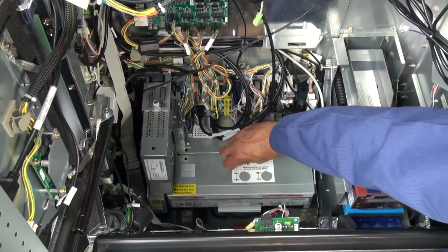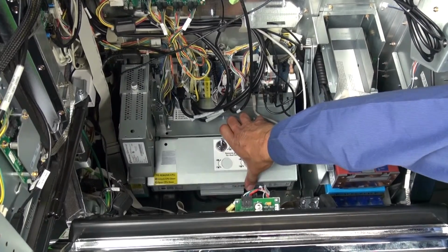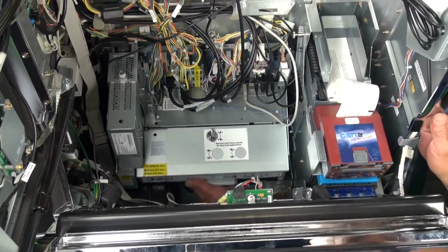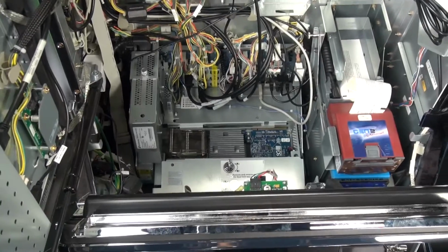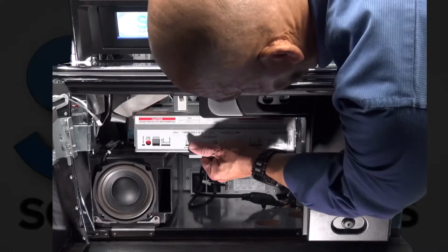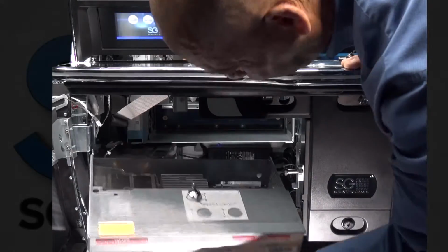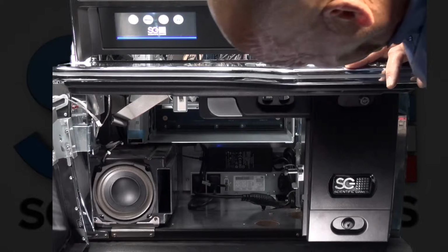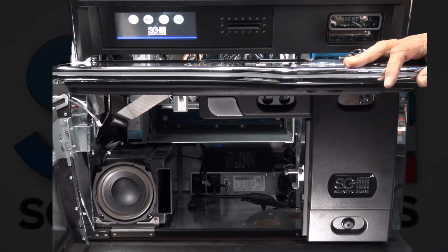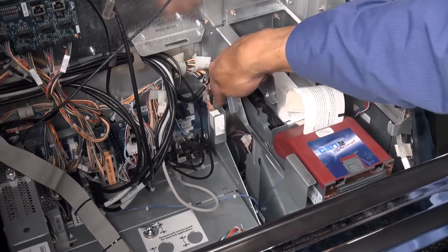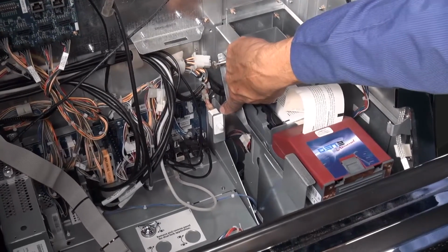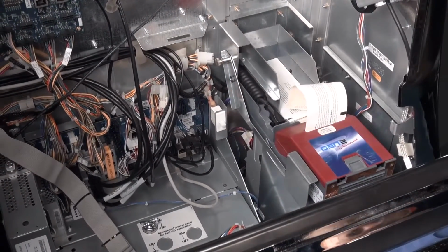To remove the CPU, open the logic door on the CPU and leave open. Using the handle, pull towards you. Twist slightly to the left to allow the right side to be more forward than the left side of the CPU. Now, pull the CPU towards you to pull out and through the belly door. To access the operator's menu, you have the diagnostic button. This is located on the right side of the cabinet towards the back and above the CPU.